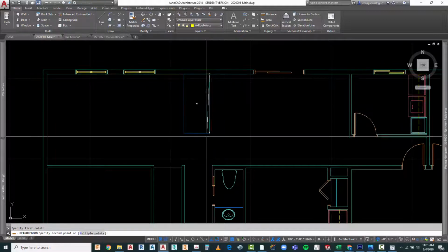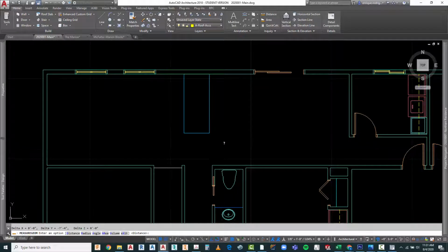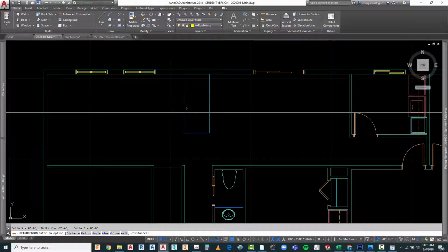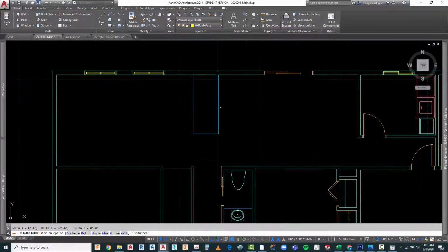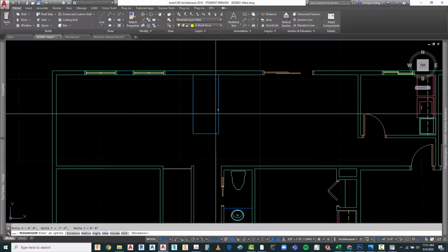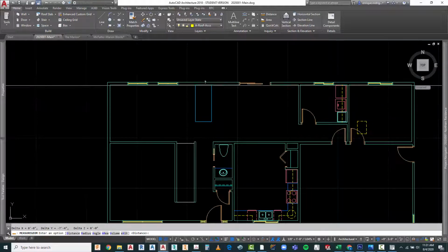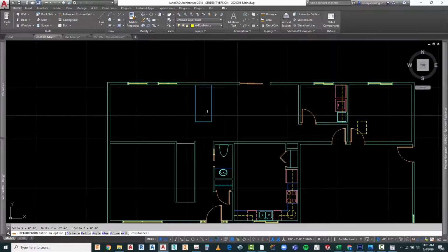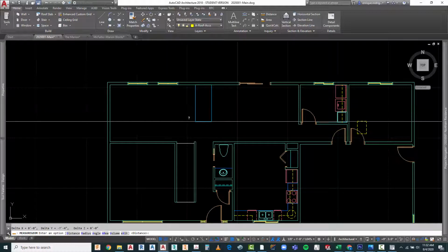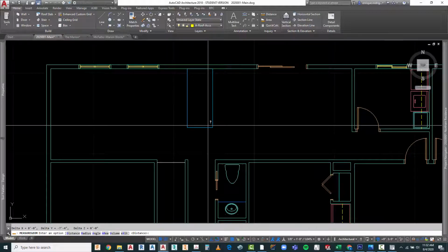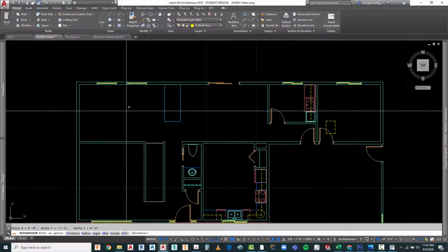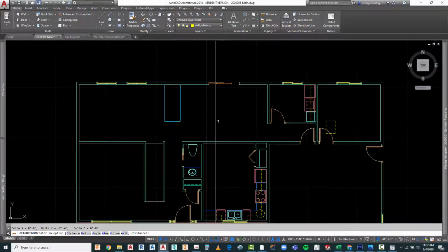Now this distance is going to be tied into, if you notice, it's only 7 foot 4 as opposed to what they showed in the red lines and the marks. We need to adjust that because our support for this masonry fireplace is located in the basement, and we made modifications in the basement in order to get corridor access and the doorways into our rooms, and also to have a cleaner look.